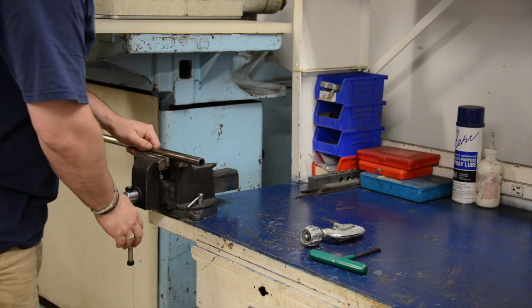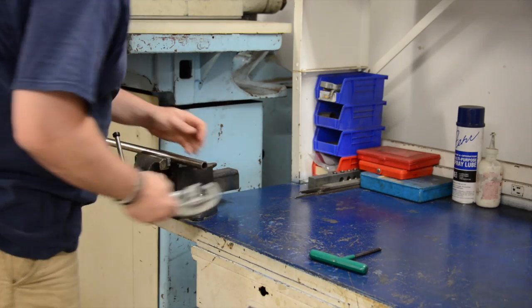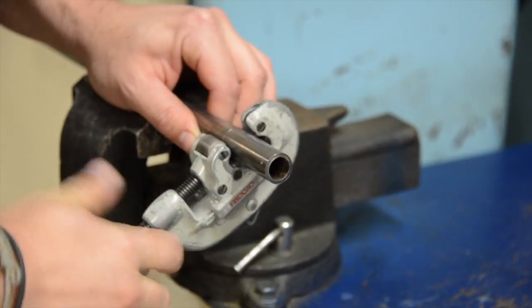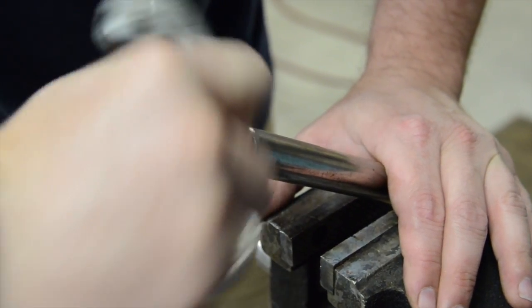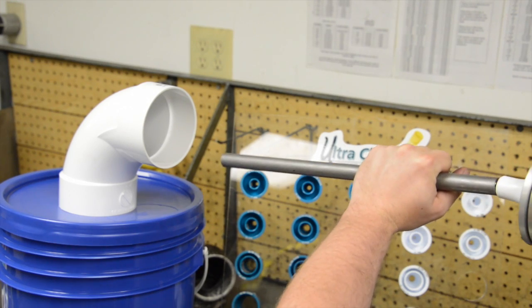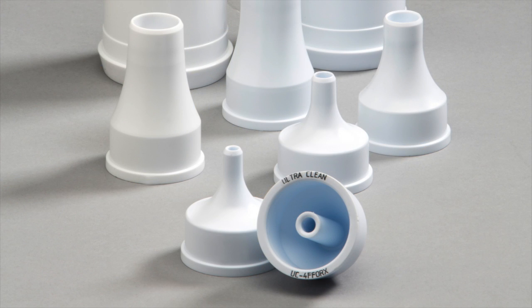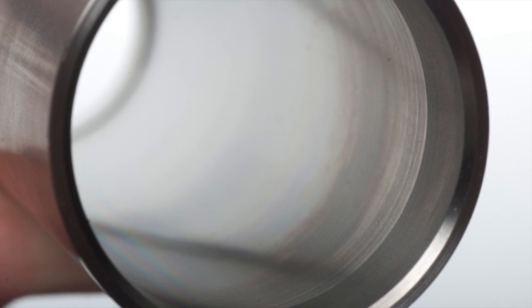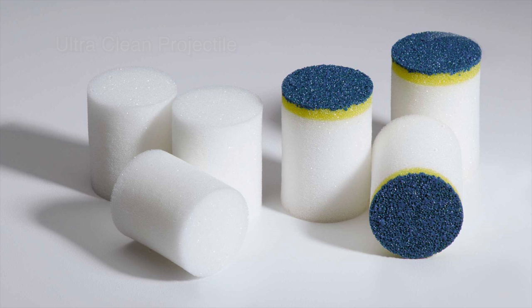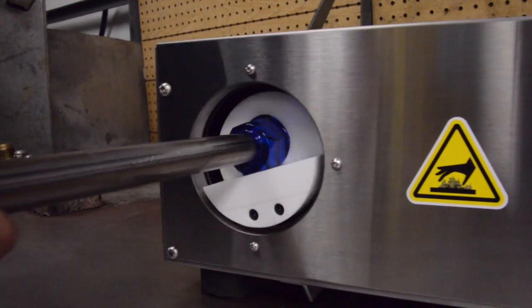Tube assemblies should also be cleaned to remove metal particles and other contaminants. Before you clean the tube assembly, you should always deburr each end of the tube. Make your bends and flare the end of the tube if required. You should always fire the projectiles from the same end because the JIC and tube nozzle will clean the entire length. If rust or oxidation is present on the inner surface, you may need to use our abrasive projectiles until it is removed. The final projectile through the tube should be an ultra-clean projectile. Repeat the capping process when you're finished cleaning.